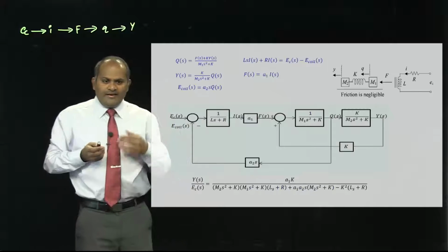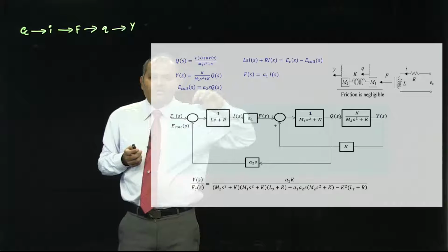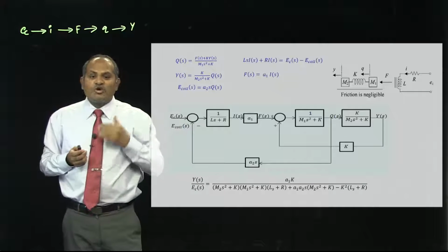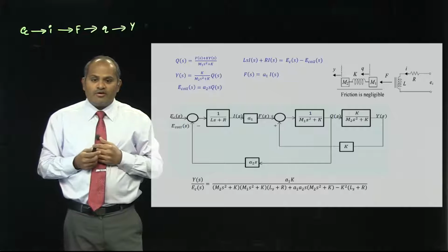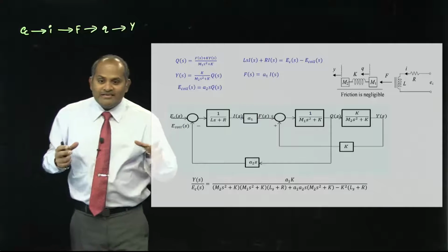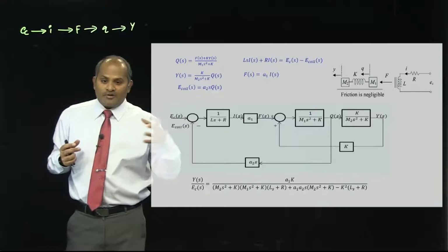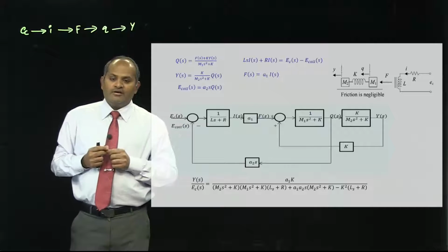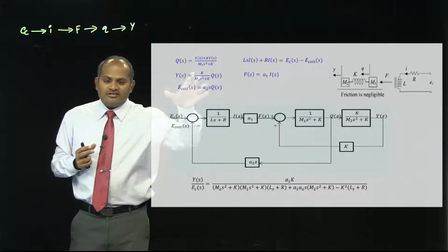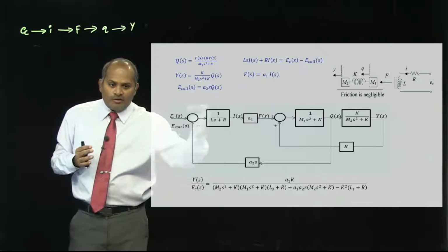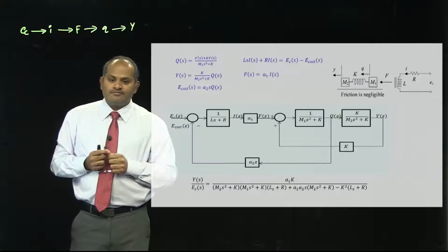So, by getting these terms and by writing all this transfer function, the most important stage is to connect them. How we connect them is more important. Connecting the terms requires the understanding of how the energy propagation occurs and what is the feedback. Whenever you have all the equations and then you want to formulate the transfer function, that is where you need to think. Believe me,